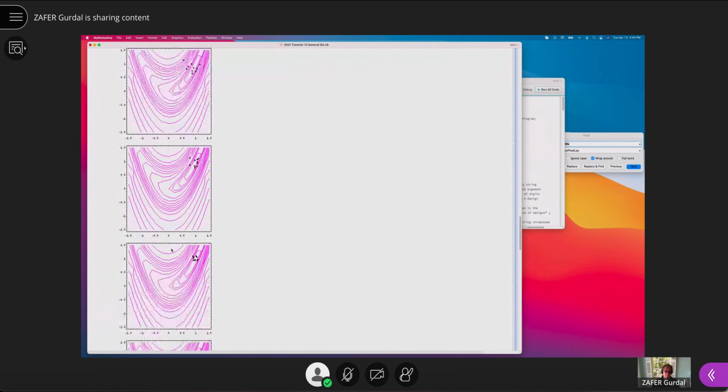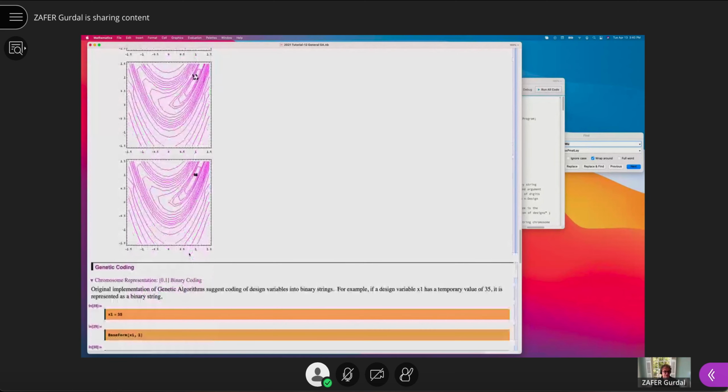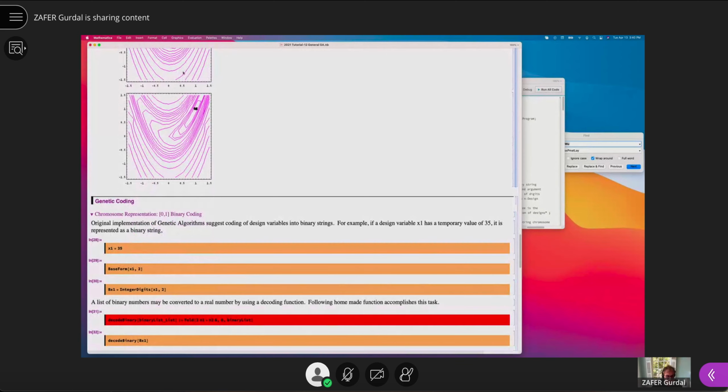And this is a typical case for composite design, that different layers acting differently may be controlling the design from different perspectives, from the strength and stiffness and the vibration frequency perspectives. So there may be actually multiple things happening at the same time. And if you formulate as one objective, sometimes this going out from a specific point, converging to a suboptimal design, will be prevented with the mutation. So that's what this is.